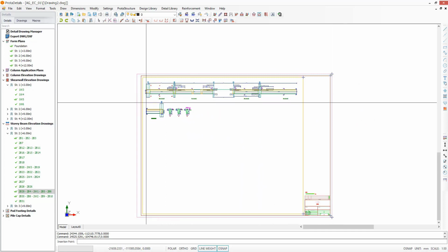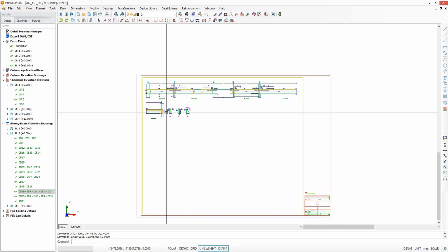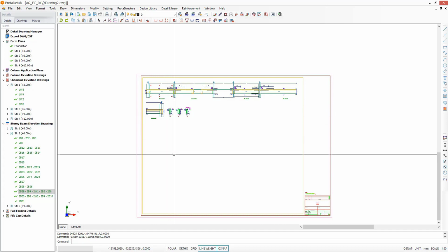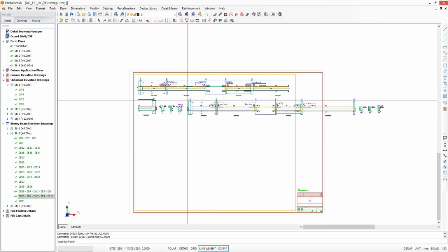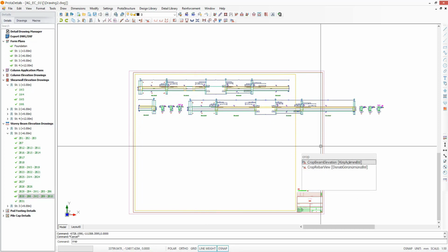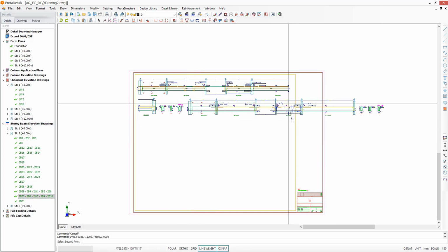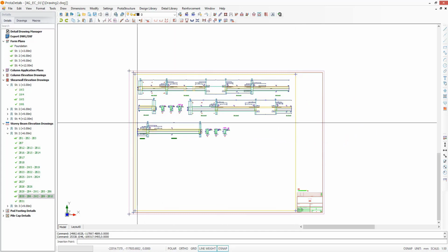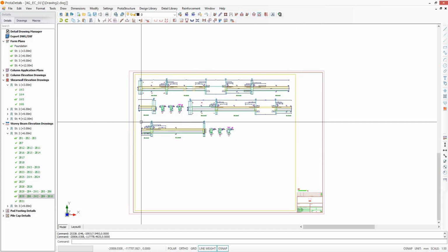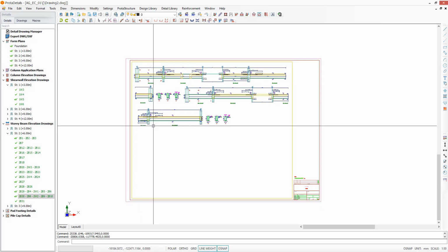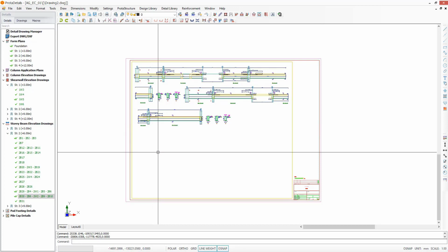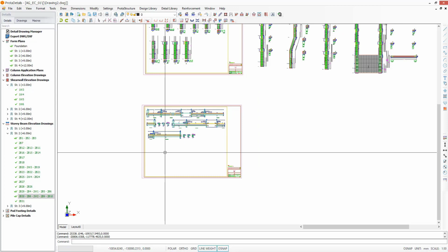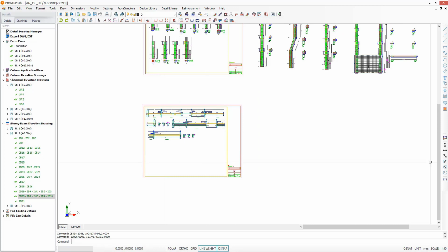and I place the crop part here, and I can continue doing this for all of the rest of the details, of course, and so on. But just remember that you could have done all this work automatically like we had in the beginning, but you have much more control when you lay out your details manually this way. So you have more freedom to organize spacing on your drawings.